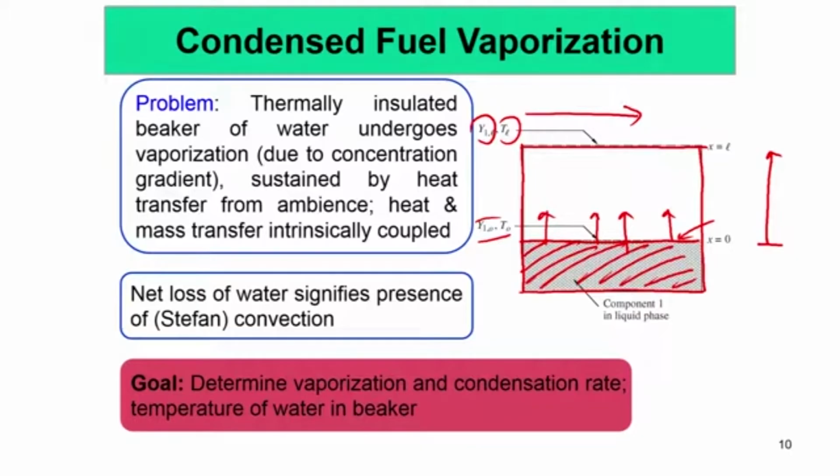Okay. So now as this liquid, which is water or a fuel, vaporizes from here, the liquid meniscus will come down, and of course the liquid is vaporizing here and going out here. So there is a continuous bulk flow of fluid that is happening, and because there is no convection inside, no pressure gradient inside, the only thing that drives it is essentially this diffusion flux.